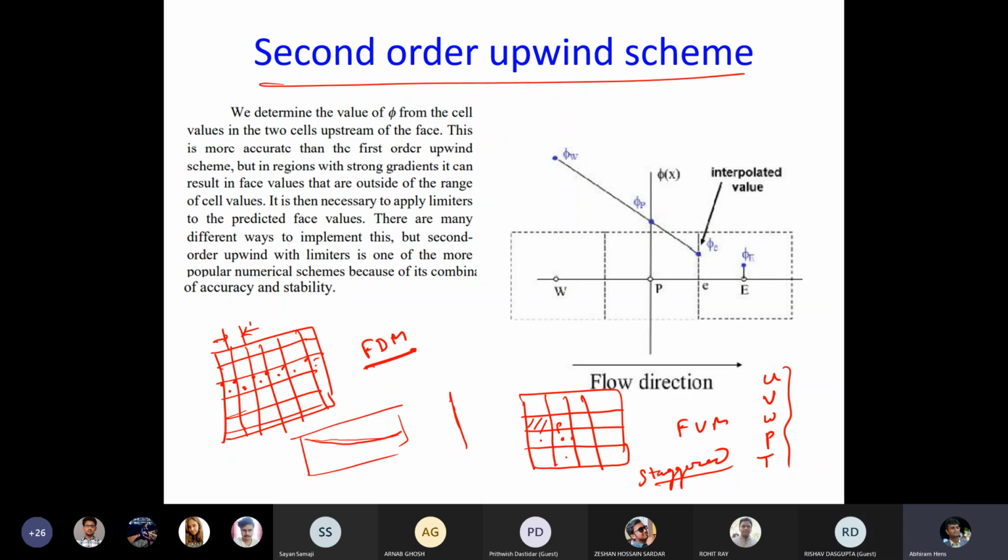Okay, but numerically, when you are solving something, because in the finite volume method you have a dy dx term in your equation, you are integrating it over a control volume. Now integration can be done only on a continuous function, right? So this has to be continuous. If you have a discrete point here, you cannot do that. At least you have to have continuity between these points, meaning your function should be continuous. From the center to the face, the value should be known, right?